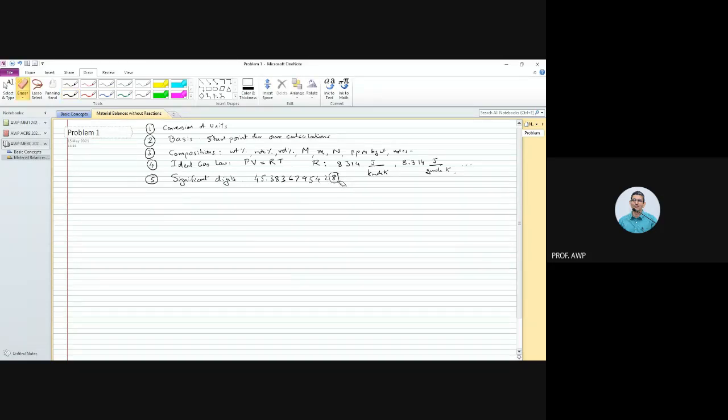Whereas our measurement accuracy of that quantity would not be that accurate. It may be plus or minus 5%, plus or minus 2%, depending on what method or instrument we are using. Correspondingly, suppose we are talking about length in centimeters, there's no point in talking about so many digits because we can't measure length up to 2, 4, 6, 8, 10 decimal places, right? Our measurement accuracy is not in picometers.